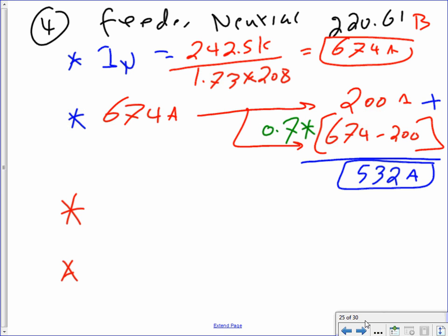Now you're going to hear, guys, if you have harmonic loads, you need a full neutral and so on. So you can always pull a full neutral. If you see your company pulling a full neutral for these, that's because they're worried about the harmonics. Okay.